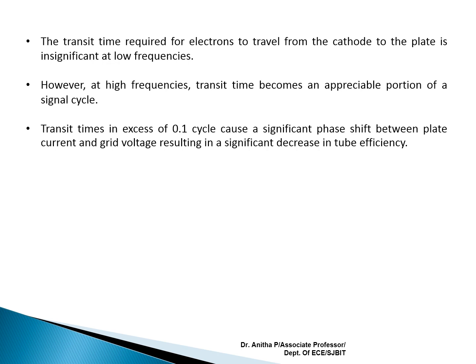Gain and bandwidth are usually inversely proportional. If I try to increase the gain, it will have an effect on bandwidth. Similarly, if I want to improve bandwidth, it will have an effect on gain. So the gain bandwidth product limits the use of the tube at very high frequency. In the same manner, there are other effects like radiation loss and skin depth effect.